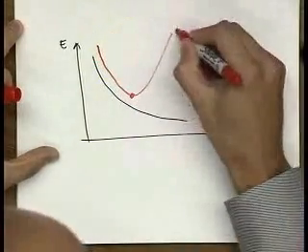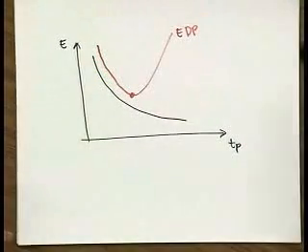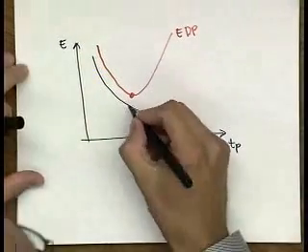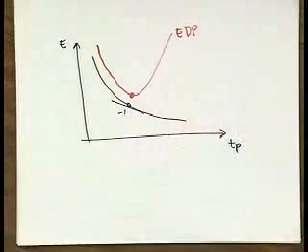So this is your EDP here. And minimum energy delay product occurs at this point where you have basically a slope of -1, which is basically the best energy performance trade-off. A slope of -1 means you can invest 1% of energy to go 1% faster in your performance.